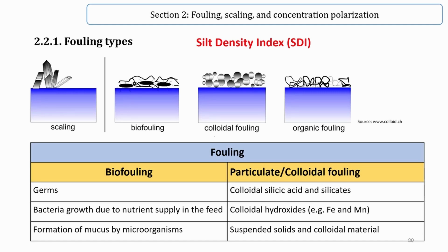SDI measurements are especially important when installing reverse osmosis systems, as these have the smallest pores of any membrane filtration systems and are consequently much more vulnerable to particulate fouling. Particulate fouling can typically be prevented by applying appropriate upstream coagulation and filtration.